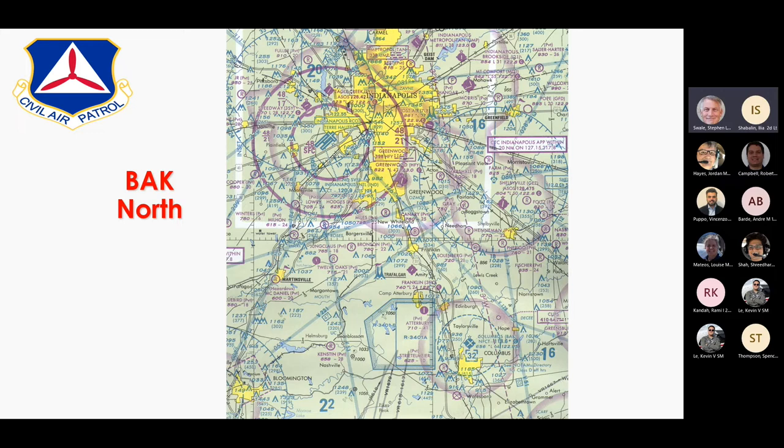They're generally controlled by air traffic control, typically the center or approach or departure. All of the information for contacting the person that's controlling that restricted airspace is on the edge of the printed paper sectional. All of the special use airspace is listed alphabetically on that, starting with the alert areas, starting with A, and then following through for prohibited and restricted areas.